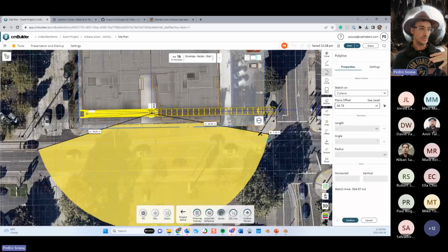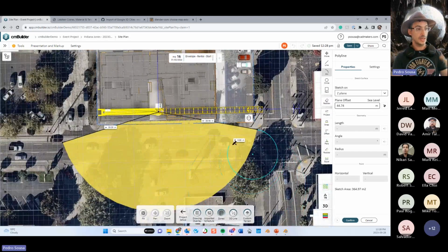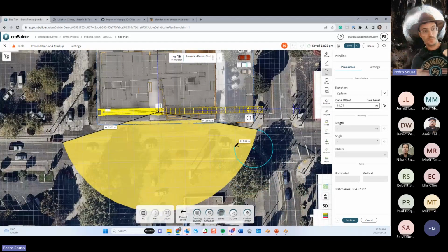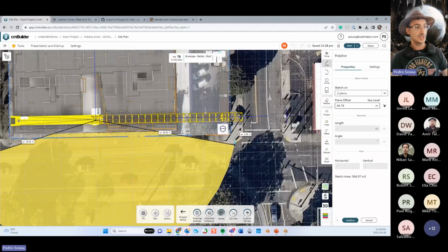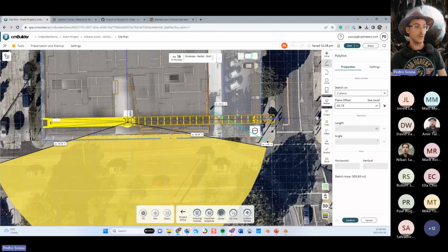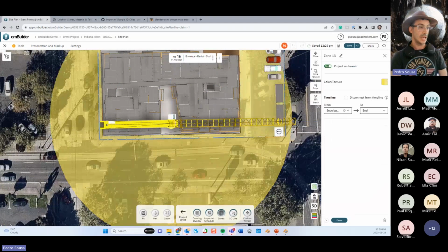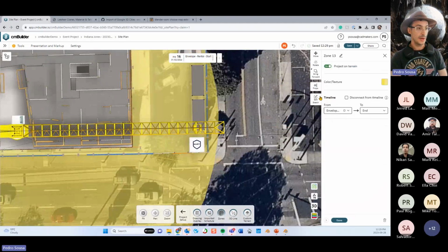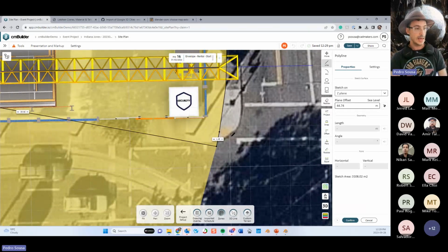sorry, the orientation of the arc is defined by whether you're tangent to one side or the other. So instead of creating an arc over here, you can create a line just to invert the orientation of that arc, and you can close this, and this line that I created over here is just to make sure that it's perpendicular and facing the other way.